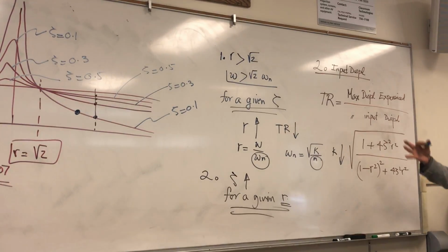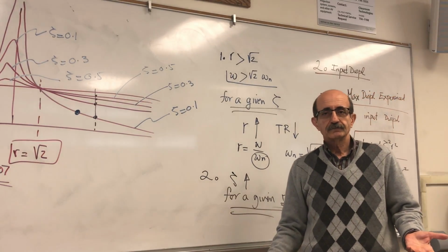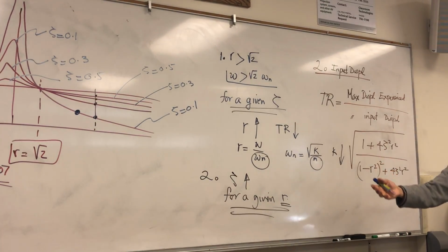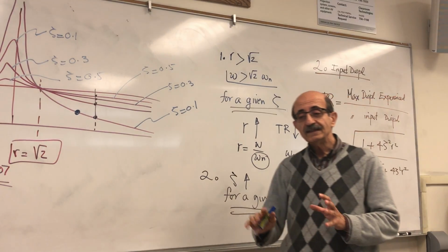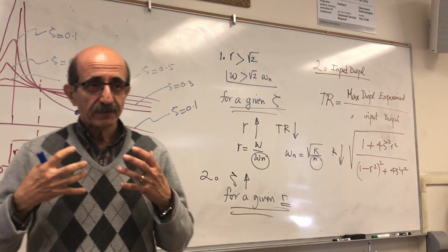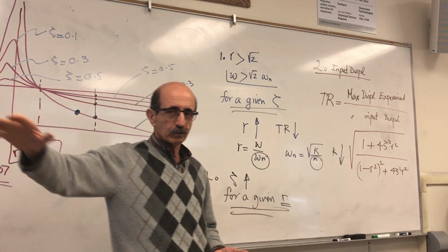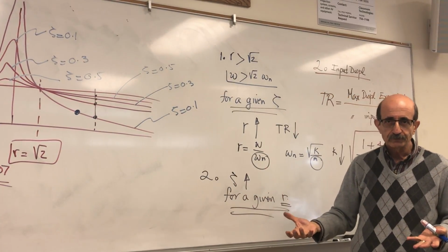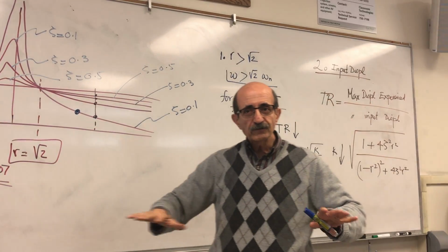So for the case of isolation, when you have an input displacement, earthquake, right? You want to have soft stiffness, low down. That's the reason it's actually easier to describe for a structural system. If you look at almost every single building in the world, if you want to design them to be better earthquake proof, you make sure that the first floor columns are very soft.